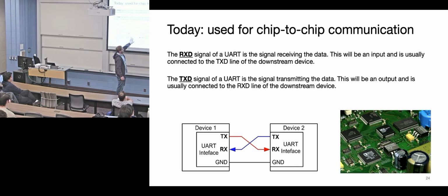You have a transmit and a receive. I know I've done this on boards where you connect your transmit to your transmit and your receive to your receive, and your board doesn't work. That was going to happen sometime in your life if you make PCBs. You just have to remember it.